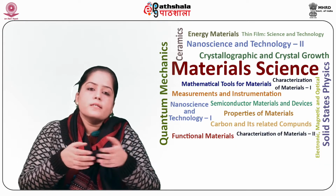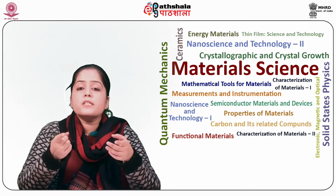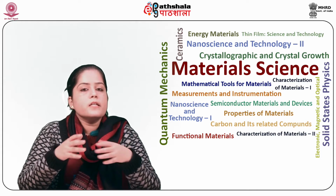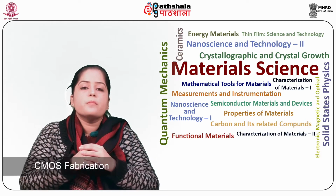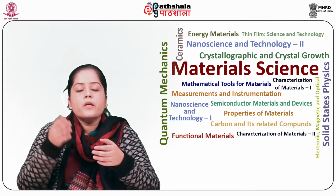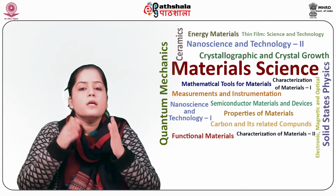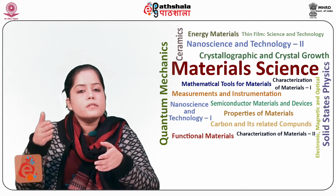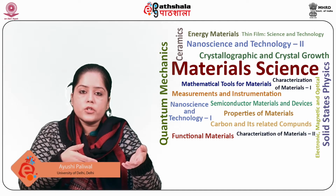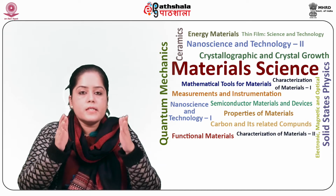So students, let us summarize what we have learnt in this module. First, we discussed the various CMOS technologies. Secondly, the different steps in CMOS fabrication like wafer formation, photolithography, well and channel formation, silicon dioxide deposition, isolation, gate oxide and gate and source drain formation, contacts and metallization, passivation and metrology. They were all discussed in detail.